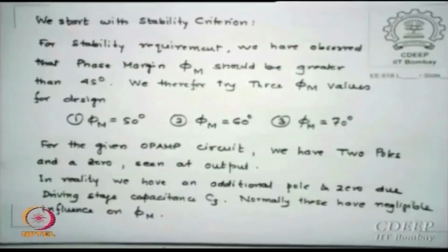So it may have a pole and a zero. What is the criteria? Because of this, the values which you are going to get, if they are larger than say 100 times or 500 times the gain bandwidth value, then I say it is damn care. Otherwise, you will have to worry about what the third pole is going to give you.